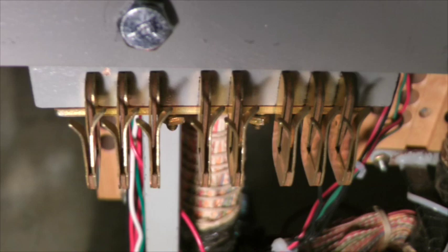The jack spring wiring provides the line finder with much of the connectivity it requires to external circuits, such as DC power, ground, wiring to the first selector, and wiring between line finders. The other means of connecting to external circuits is through the wipers. This electrical connectivity arrangement makes the line finder a plug-and-play device. It is easily removed and installed for maintenance purposes without any wiring to disconnect.